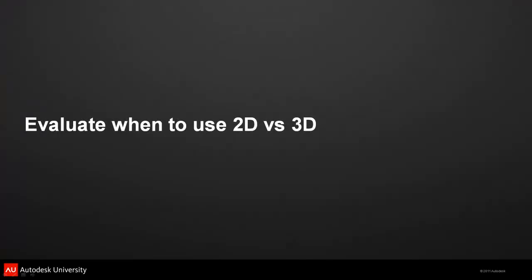In this session, you learned how to evaluate when to use 2D versus 3D by learning how to use the wall sweep tool and also when to use filled regions and detail lines appropriately.